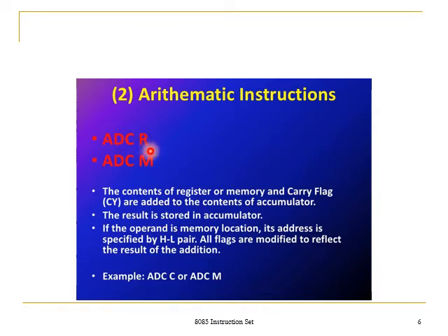The content of the register or memory, and the carry flag in the program status word, are added to the content of the accumulator. If a carry is generated while performing any addition, that carry, the content of the accumulator and the content of the register or memory are all added, and the result is stored in the accumulator itself.